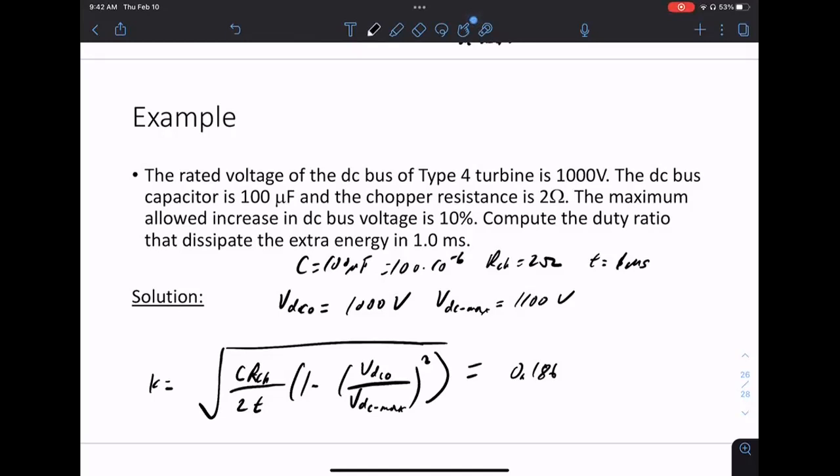So in reality, what happens is you don't see a constant voltage during a transient. You see a voltage that goes up and down. So this is actually adjusted quite dynamically. You measure the voltage, track how long this has been, change K a little bit, then measure the voltage again, then change K a little bit. So here for simplicity, you're given the average value. This thing lasts for 1 millisecond. And this is the voltage increase we have seen.